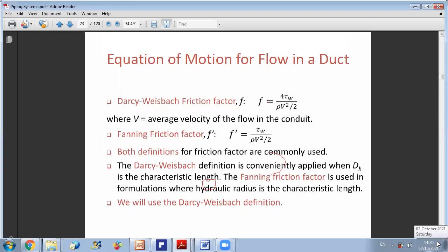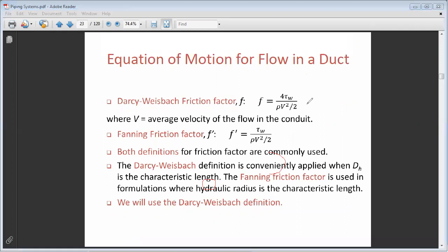Okay, so let us remember a little bit how to do this procedure. You know that always in fluid mechanics, or in experiments, to reduce the number of parameter studies we do dimensionless analysis. We ask how many groups are enough to make the experiment. For example, in the fluid problem we are working on now, we have the Reynolds number, which is related of course to the velocity of the flow, and is defined as the ratio of inertia to viscous forces.